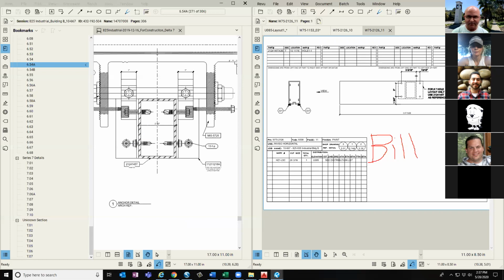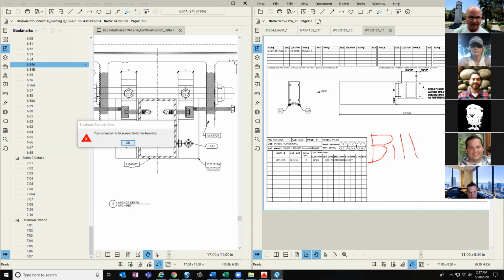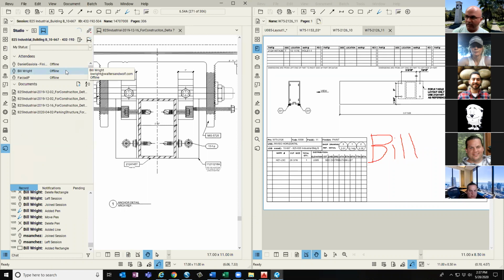I just commented that prototypes, it's not changed from prototypes to the job. Prototypes are always done with the standard face of the system, which is 2 1/4. And whenever you look at prototypes, regardless what you have on the job, it will be standard face of the system. So in some cases, you will not have it matched. Duly noted. And that's why we don't just go directly off of the layout that we see. We have to verify what's happening very specifically with the shop drawings. So we always go back to the shop drawings for our reference.